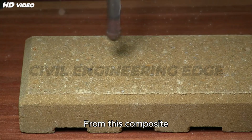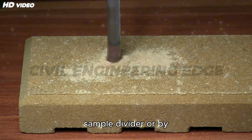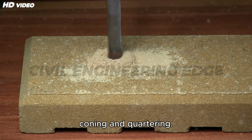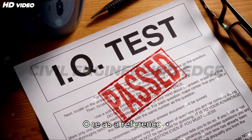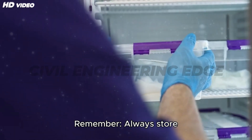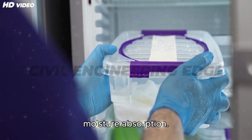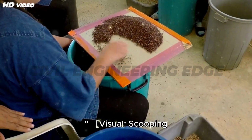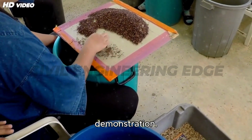From this composite sample, divide the cement into 3 parts using a sample divider or by coning and quartering. These are: 1 for immediate testing, 1 as a reference, 1 for retesting if needed. Remember, always store samples in airtight containers to prevent moisture absorption. Visual: scooping from bags, mixing, coning, and quartering demonstration.